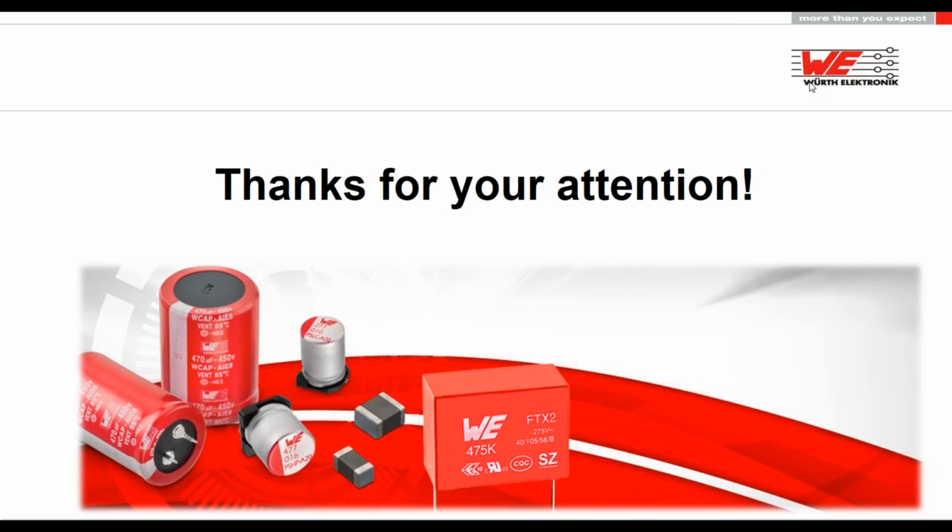Yeah, also for the MLCCs, we got asked if there's any safety margin in case of voltage related to the rated voltage. As a manufacturer, we cannot say, hey, go over the borderline and everything will be fine. Yes, sure, there is a certain safety margin in case of surges, and especially for spikes. But if you continuously go over the rated voltage, over time you can damage the dielectric, because the thickness of the ceramic layers is not made for higher continuous DC applied as stated in the data sheet.